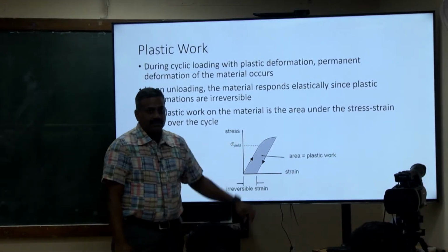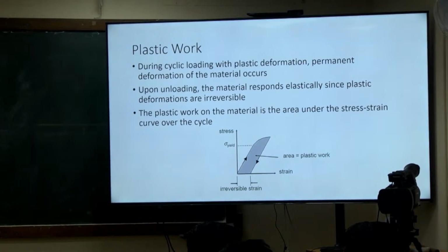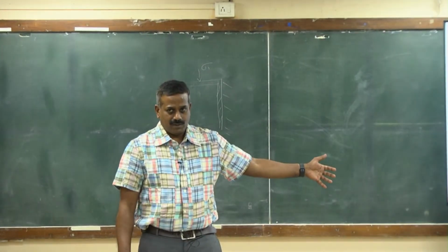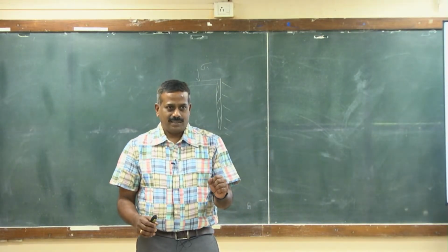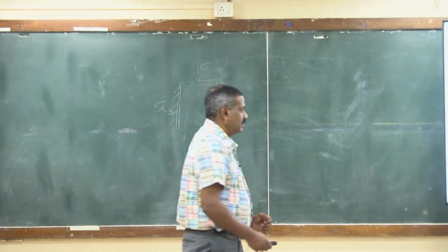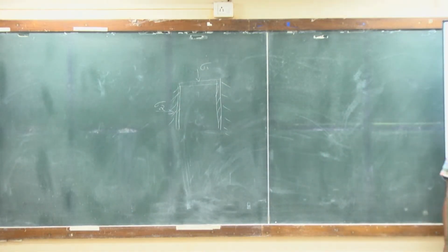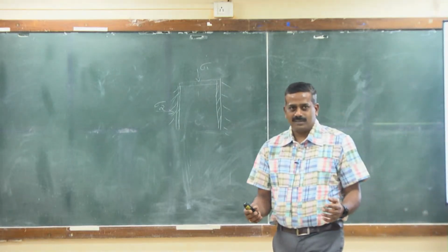The difference between the compression and the loading and unloading curve, after it exceeds the plastic limit, is called the plastic work. So it is the energy that the material loses between multiple cyclical compression loads or tensile loads. Okay. So what example can you think of where we apply this?